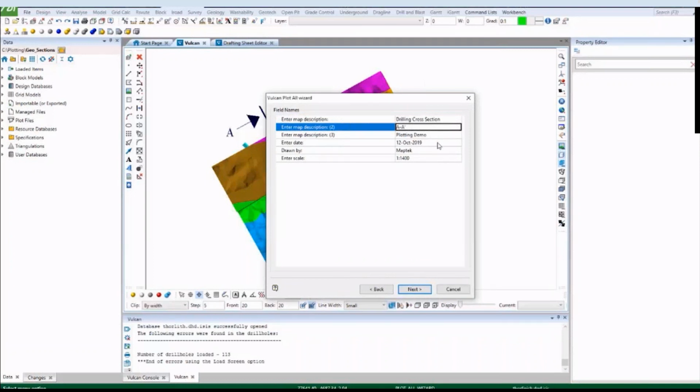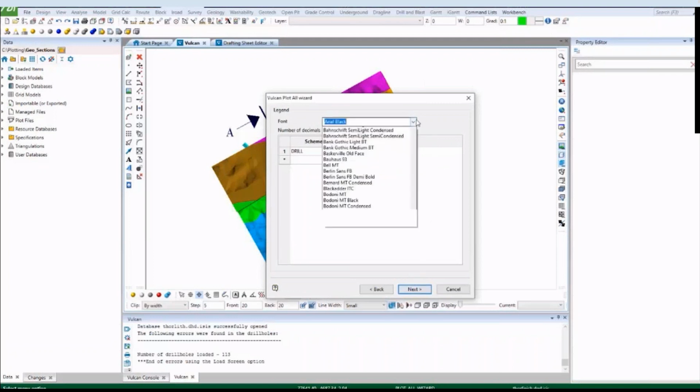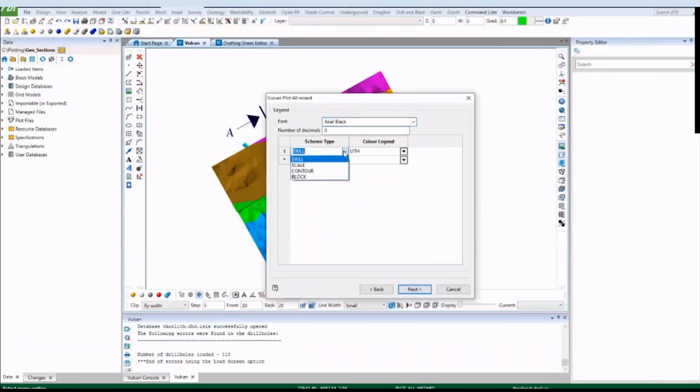Now, filling out my title block, you can use plot variables, which quickly just automatically pull in, say, the date, or pull in the scale. Here we're using scale 1, so it's going to pull in the scale for viewport number 1. There are a long list of plot variables in your help. Definitely check those out. Here we're picking out the legend.